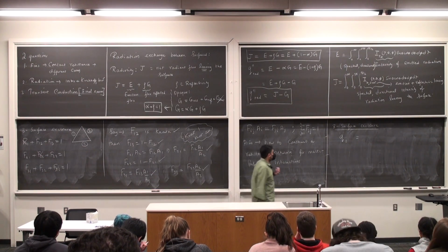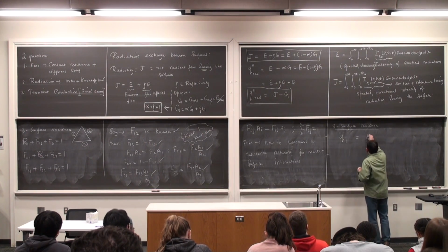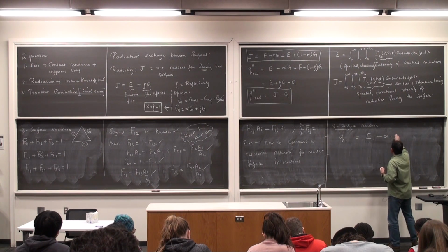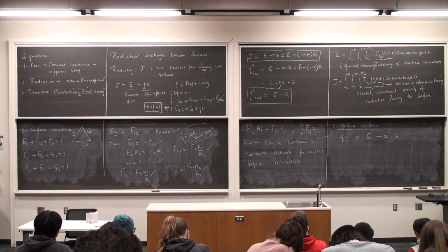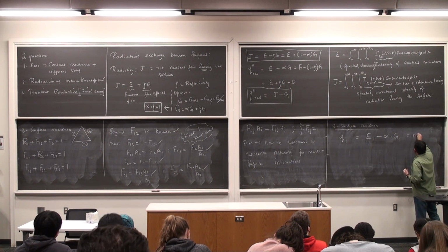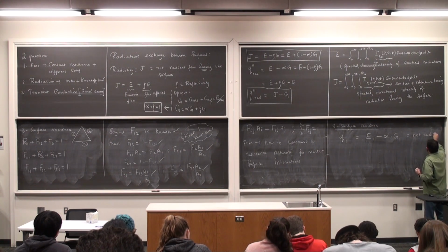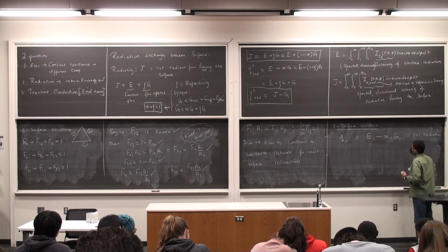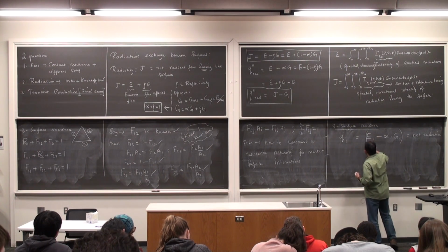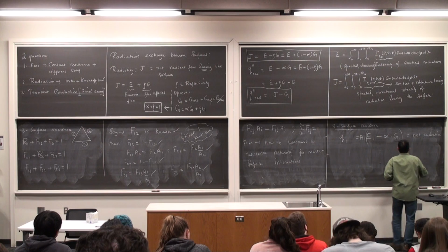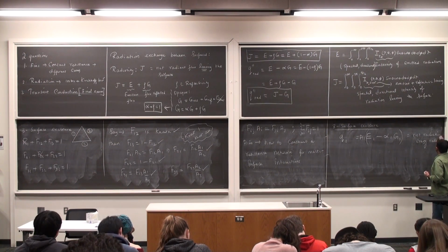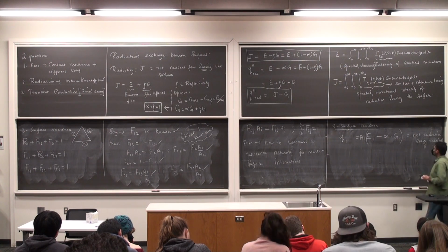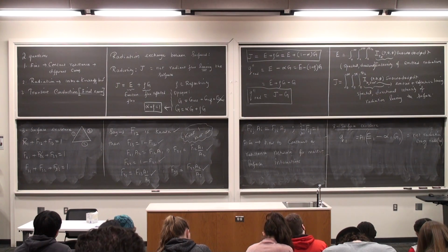Okay, so this is going to be E1 minus alpha 1 G1. Okay, this is the net radiated flux. I guess multiplied with the area, so net radiant energy. Energy rate in watts from surface 1.